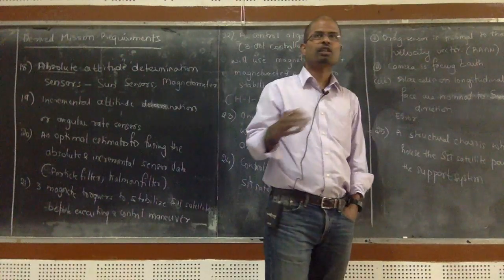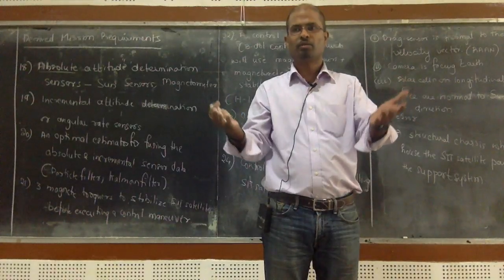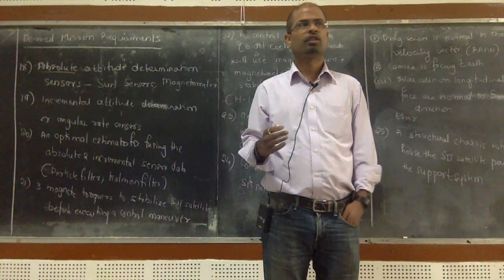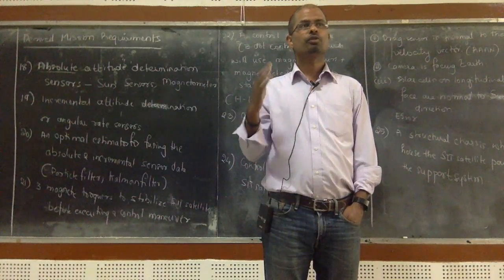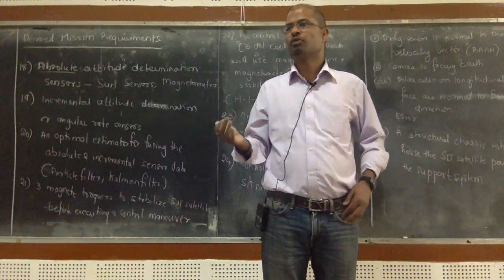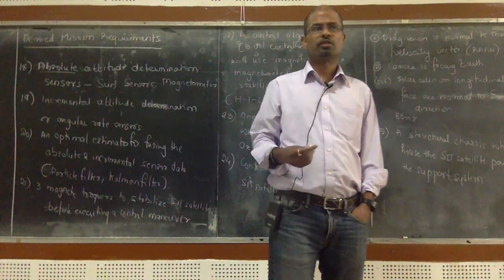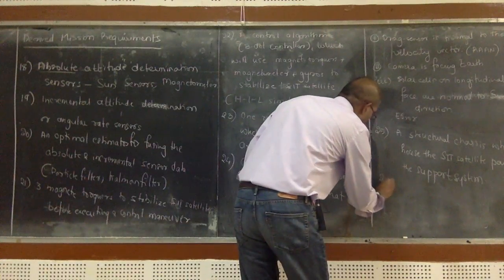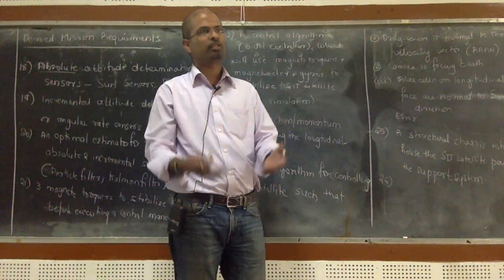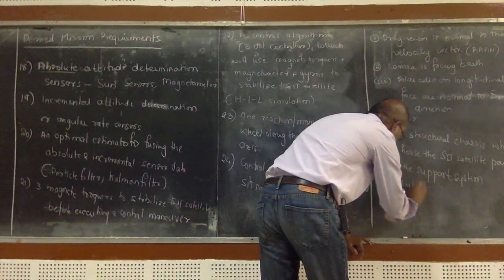So I'm going to show you the satellite. Typically you can design metal panels as well, aluminum panels, but it will make the satellite a little too heavy. So what we are going to do is use PCB panels to, one, cover the satellite, plus it will also be used for mounting the solar cells. So that's the reason I'm saying not just the solar cells, but also other cameras, sun sensors, temperature sensors, all that. So that is the reason I'm calling them multifunctional